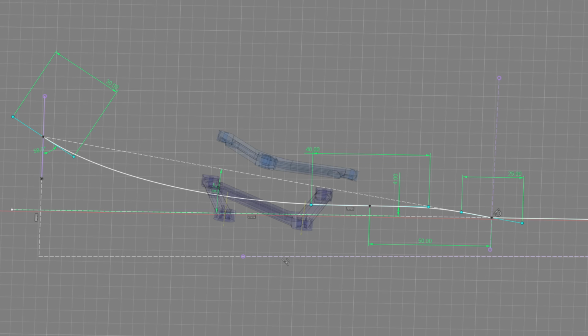This isn't always as efficient as a single kick-up point diffuser, but it does help to balance the aero downforce on the car, and the first kick-up point is not as badly affected by the tire squirt or the wake coming off of the rear tires, which can be beneficial.